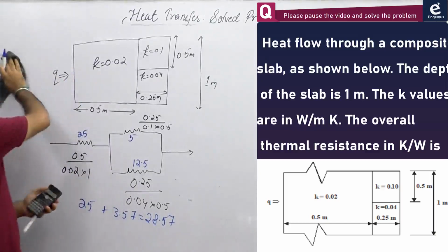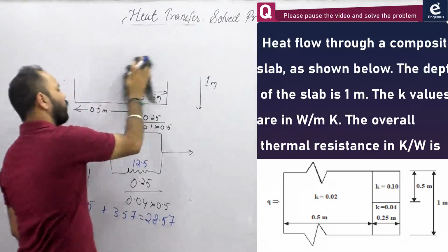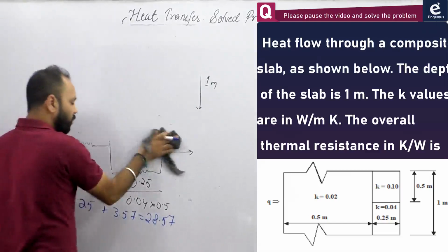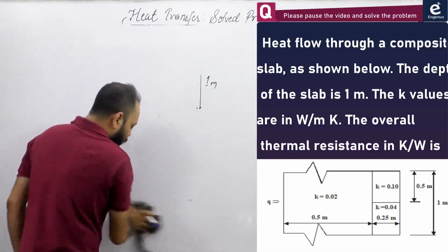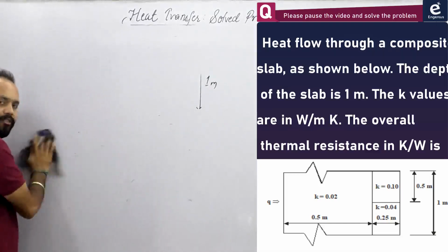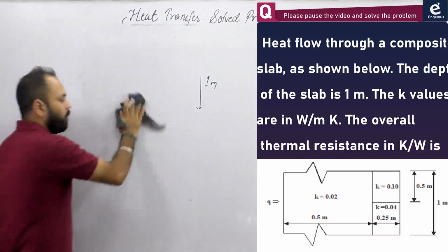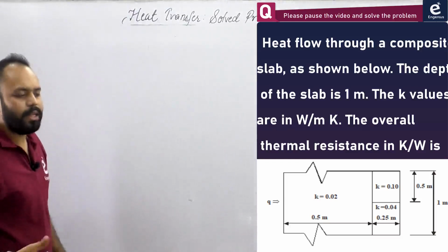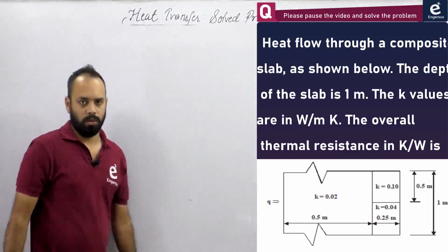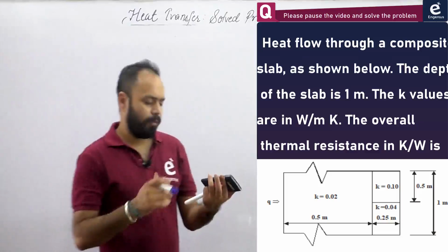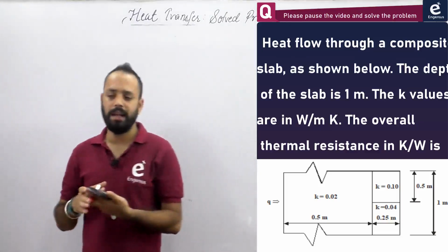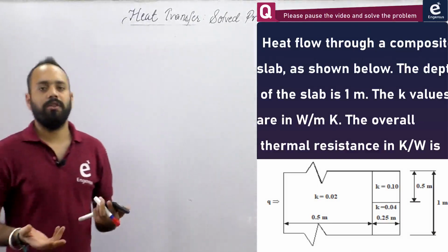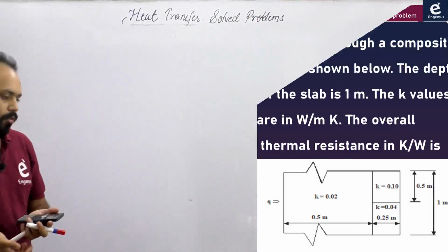Note down, questions like this have come in Mechanical as well as Chemical. I have also discussed this condition with you. Once a student asked me, sir, if the parallel bodies have different thermal conductivities, how can the temperatures be the same? In that case, we can have different heat fluxes. Somehow, with the help of some kind of arrangement, I am maintaining similar temperature on the right side of the wall. But if K is different, then ultimately the heat flux through the body will be different.